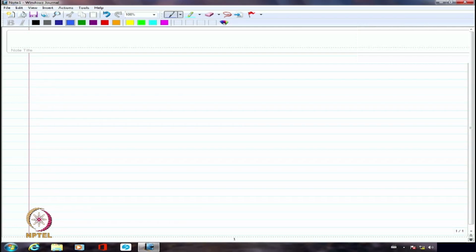Whereas, the 3rd type of speed control scheme, which is field flux or field current control scheme, looks at the flux going below the rated value, because of which the torque capability will also come down, if I am assuming that the armature current should not go beyond normal values. So we are looking at field flux control only for above rated speed operation, but with the torque being below the rated torque value. So when we multiply both of them, we are going to have constant power.